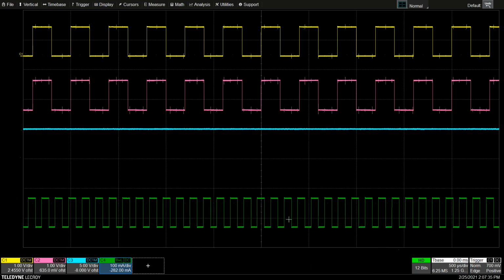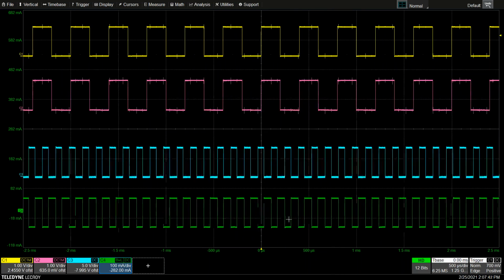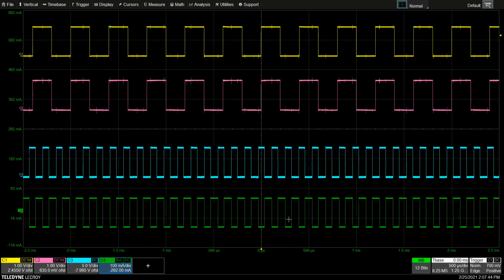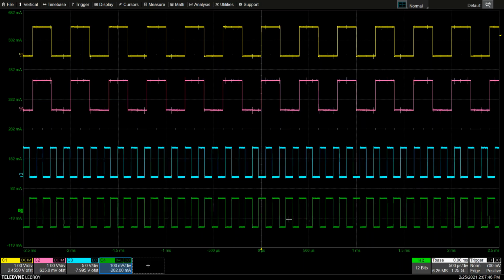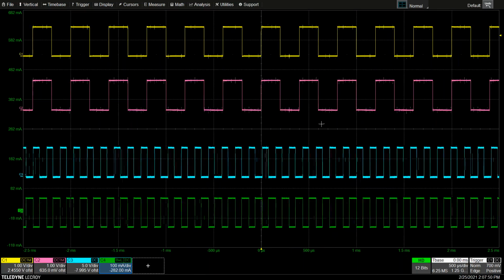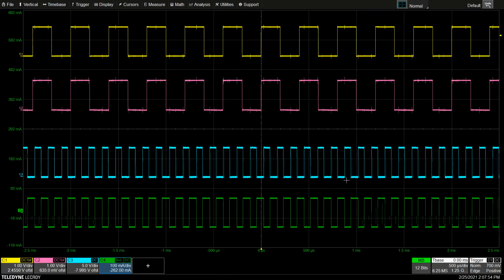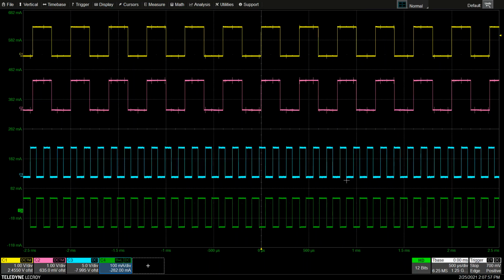Channel 3 is disconnected, I believe. And hang on one sec. Murphy's Law always follows me around. There we go. So these, channel 3 and 4 are asynchronous to channel 1 and 2. Channel 1 and 2 are hooked up to the calibrator. 3 and 4 are asynchronous. So I'm just going to go ahead and do a single shot so we can see these are our 4 waveforms, and we've reduced them just like the slide set showed.